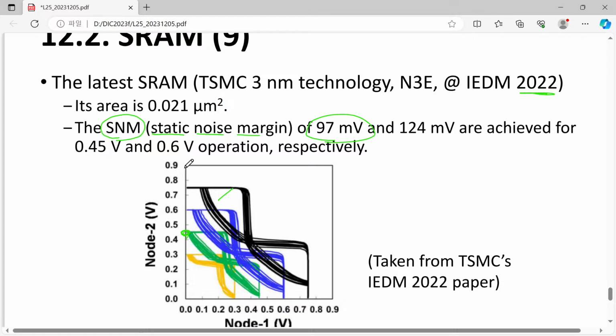It has a P MOSFET and an N MOSFET. They are mismatched, and they have capacitors inside, and they have a certain voltage margin to be turned on and turned off. Also, they have leakages. There are tons of non-idealities in this device. However, within that limitation, people have developed ways to optimize it and to minimize the delay, power, and area.